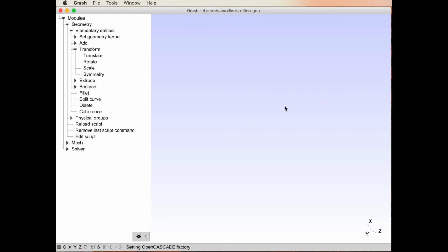If you click an entity and click translate, you can translate it. Extrude is another simple one. We can translate, rotate, and create a pipe. So if we have, say, a plane, we can extrude it or rotate it with translation or rotation to make like a cylinder or a box with these two commands respectively. Easy. Boolean is interesting. So we can take two shapes and find their intersections and create a new shape.